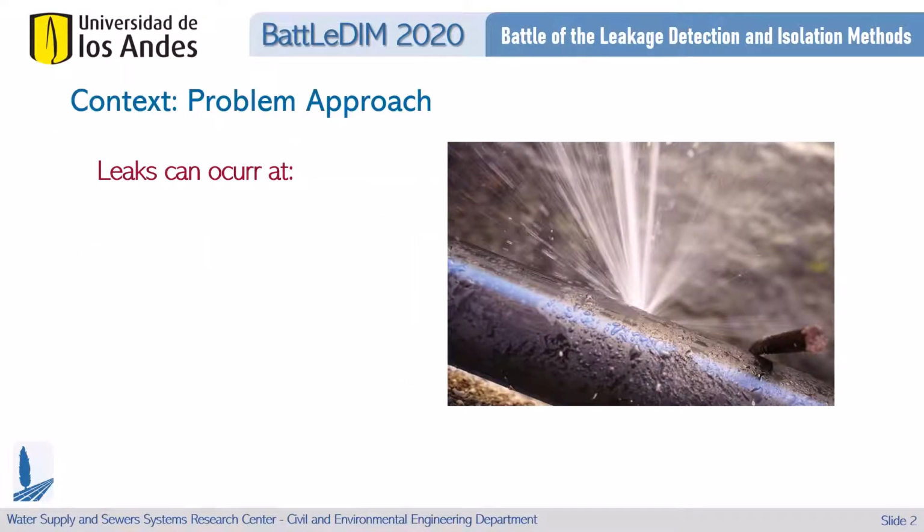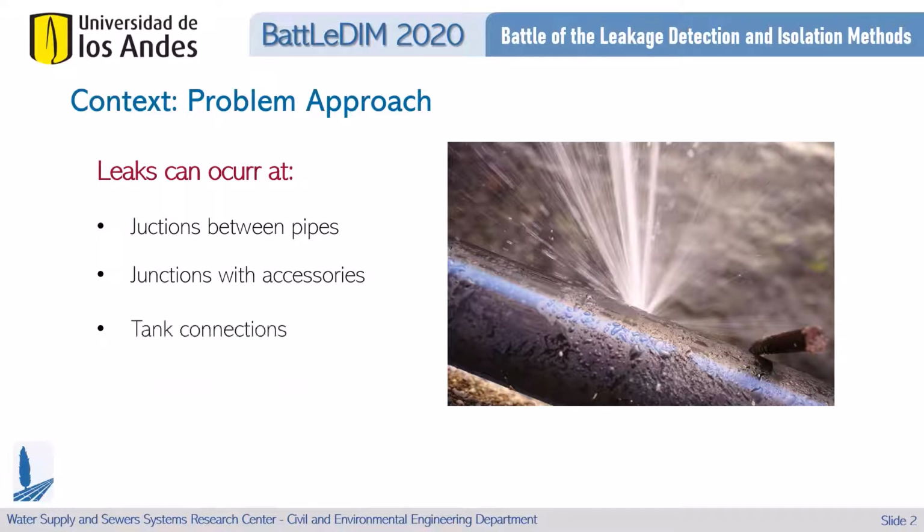In water networks, leakages can occur in junctions between pipes, breaks in the pipes, or accessories that form part of storage tanks and compensation tanks. In addition, leakage can happen due to the movement or settling of the ground, traffic, or poor quality materials.